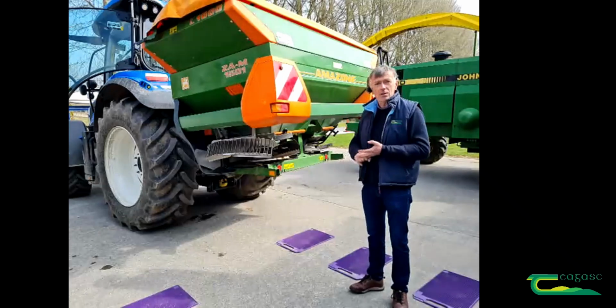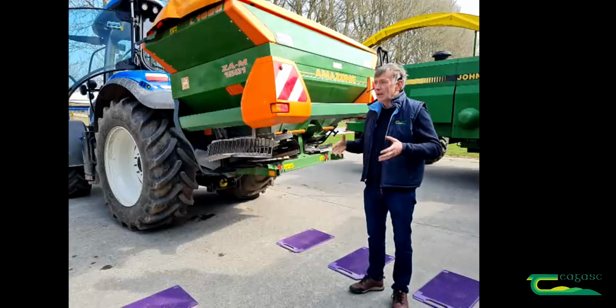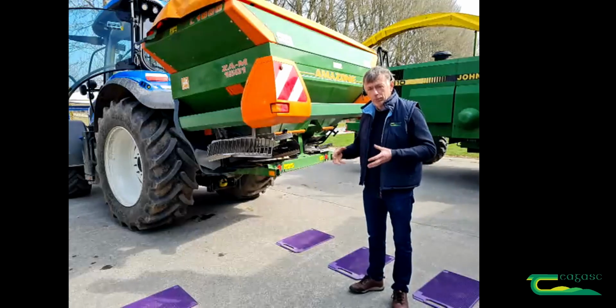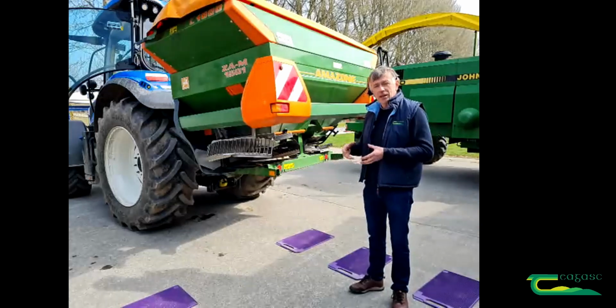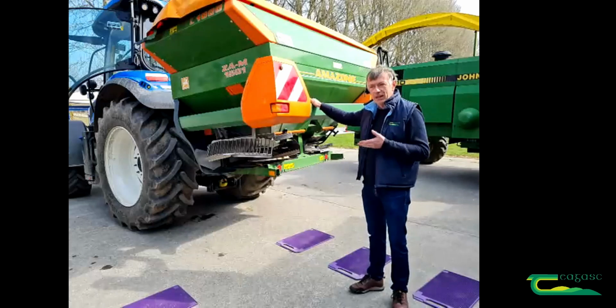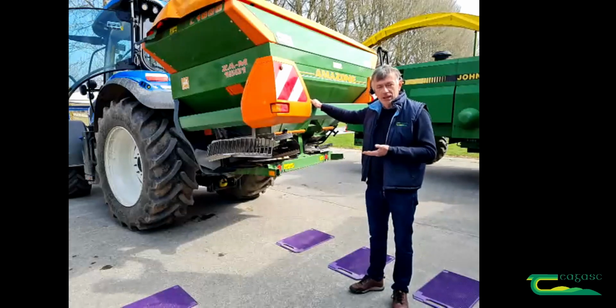And that really gives us two, I suppose, advantages. One is that the calibration procedure that you need to do to get the correct flow rate, to get the right application rate, can be done automatically. So by having constant weighing of the system, it allows you to do that. It's self-calibrating in that kind of context.